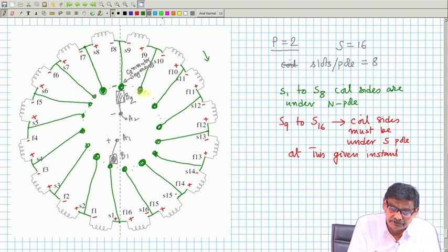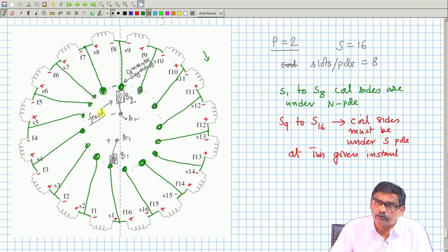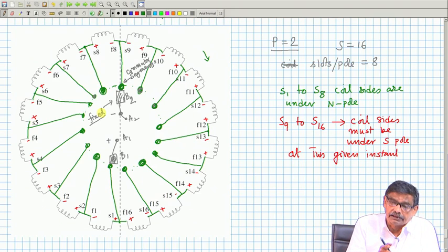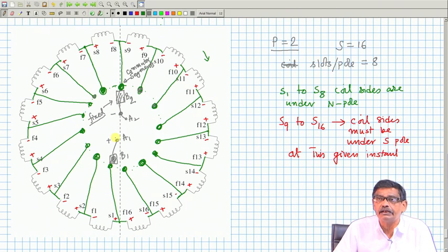Each thick copper strip in this representative diagram, and these are fixed brushes. So, in the armature winding of a DC machine, coils are connected in series. Then you will have two additional things. One is commutator segments, as many commutator segments as the number of slots, and there will be 2 or 4 brushes or 6 brushes depending upon the number of poles, if the winding is lap winding. That is what I told you.